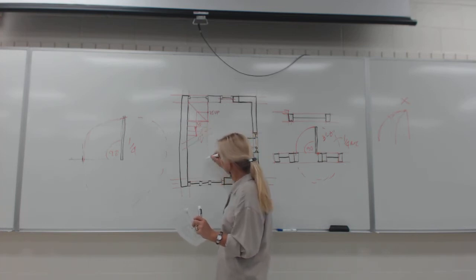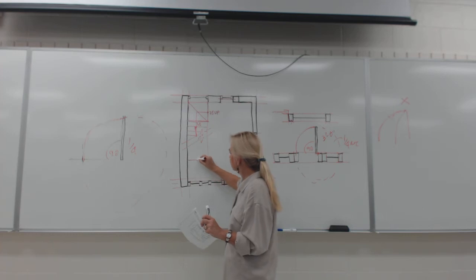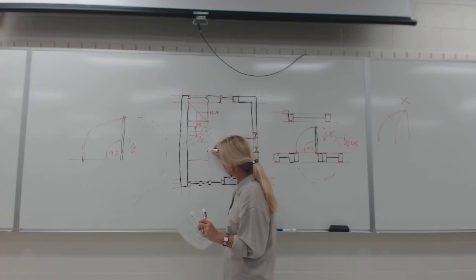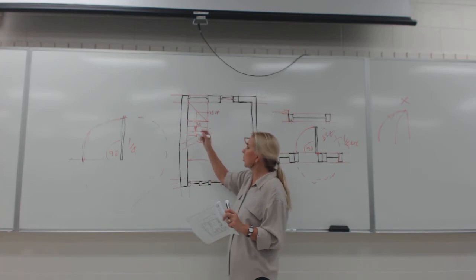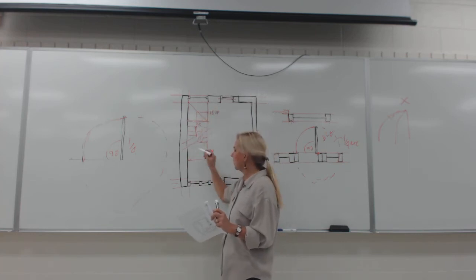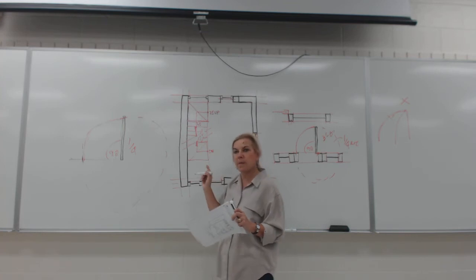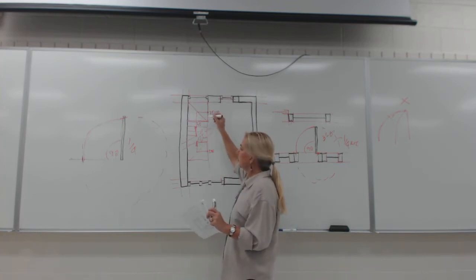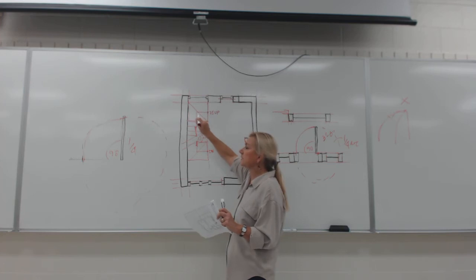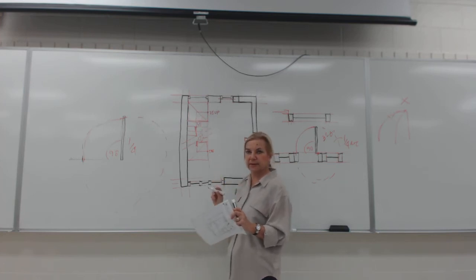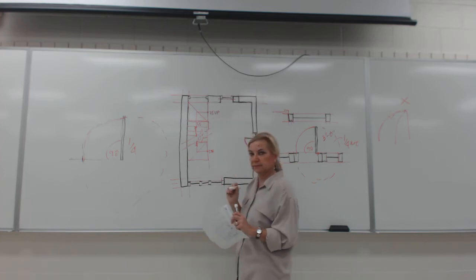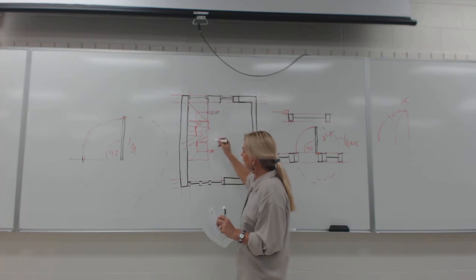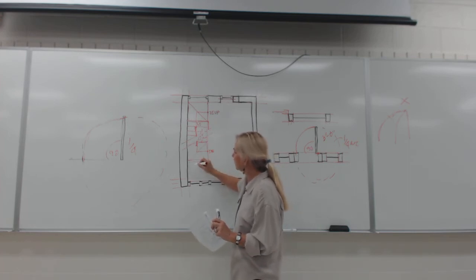And then from the other side of the house, now it's different. I'm going to draw it slightly bigger. We're going down. Down here on 45 and again. So we're going to show part of the stairs going up and part of the stairs going down with 2 arrows on the main floor. On the upper floor, you will see only this stair because this stair will completely cover the stair going down, okay? Now, from here on is a 1-inch railing. So we're going to show the railing here and whatever happens on this side.